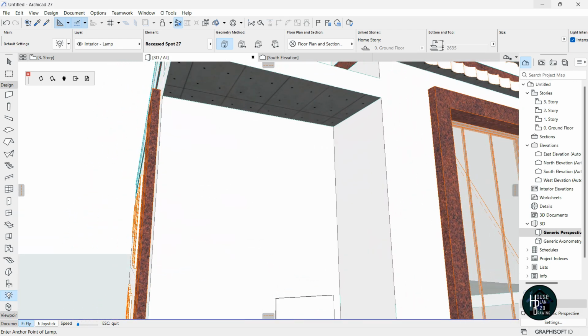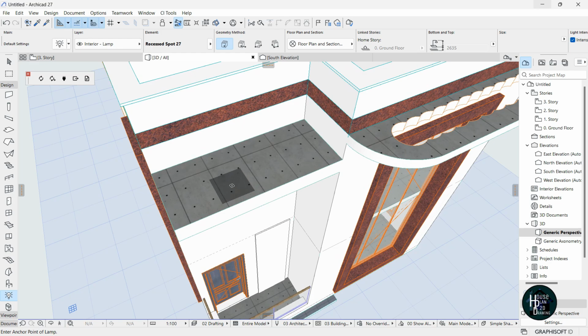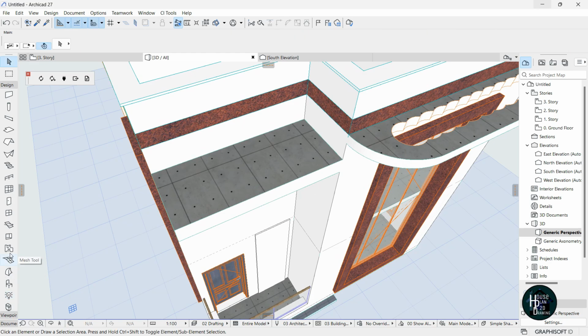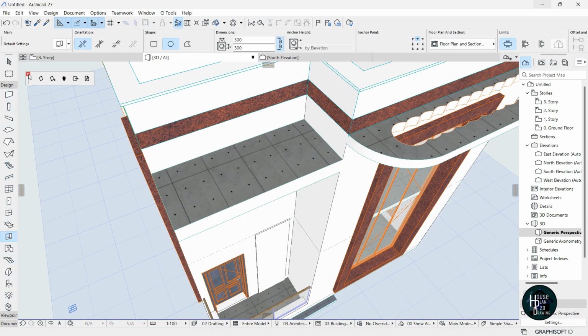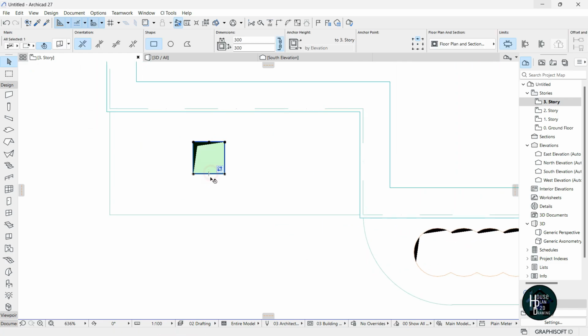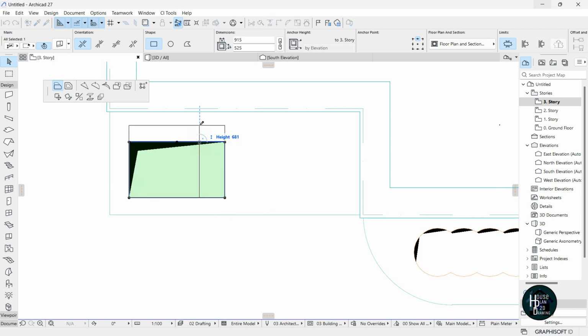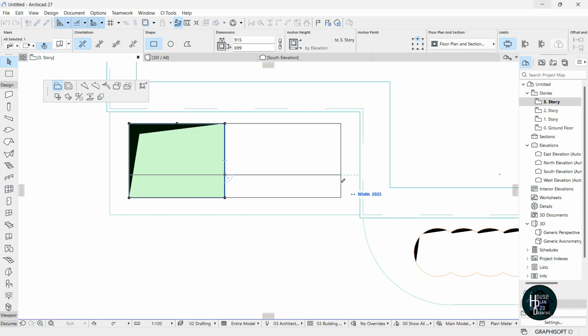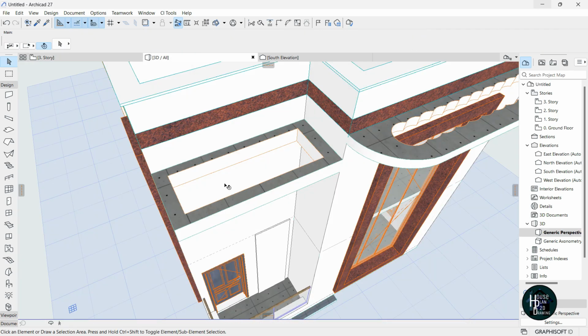Now for this side too, we're going to do the same design by, we want to open it, so we're going to click on the opening tool here under design, okay. This is the opening tool under design. Just click on this rectangular and just click. Once you click, go to, you're going to be seeing it here. Click on the circular itself, click on this edge, come and select this offset edge, and just try and make a nice rectangle shape, like so. Once you do this, go to your 3D view, and I'm going to be having it being opened like this, okay.